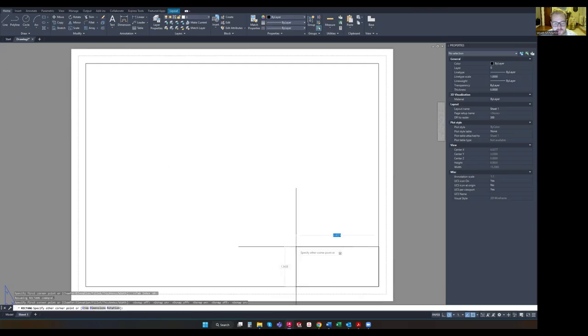And now we're making another rectangle. So it's asking for your horizontal dimension first. And we're going to type 2, enter, and then 0.5, enter. Oh, I'm sorry about that. Hit your rectangle tool. I missed a step.